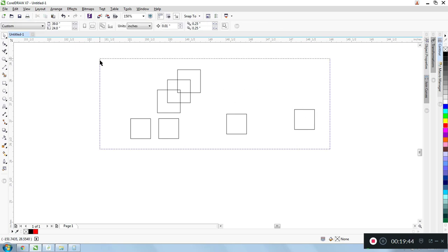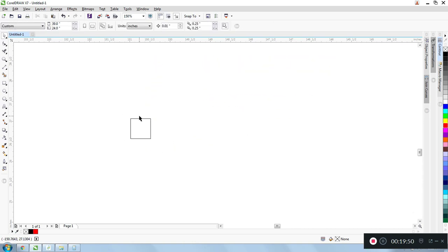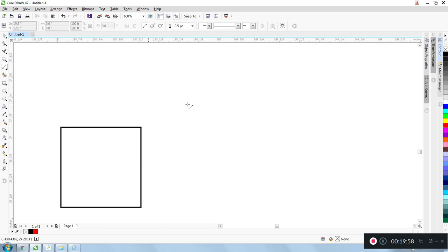So this is a great layout tool. If I have a bunch of cards, coasters, whatever, all the stuff we always laser cut, and I want to lay them all out in here instead of in the laser software, and I want them all to be 1/8 of an inch apart, I draw a 1/8 inch line. Here we go, if you have lock ratios engaged, you can't change the dimension of lines.